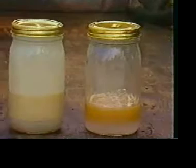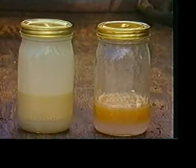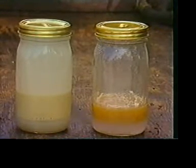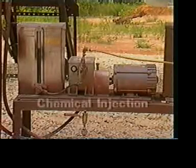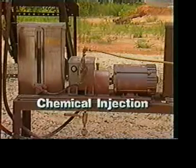As you can see, there is a difference. In only a short time, the heated emulsion has separated more than the unheated emulsion. But heat should be applied only when necessary and as little as possible, because too much heat will waste energy and cause greater wear on equipment. Also, excessive heat can burn off the valuable lighter ends of crude oil, changing the oil's gravity and resulting in lost revenue.